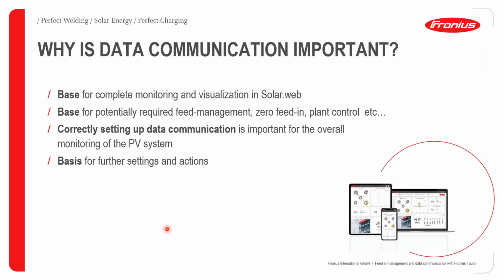Why is data communication important for a PV system? Firstly, it provides a basis for complete monitoring and visualization in our online monitoring platform, which is called solar.web. It also provides a basis for potentially limiting feed-in to the grid, also for setting up zero feed-in, plant control, etc.